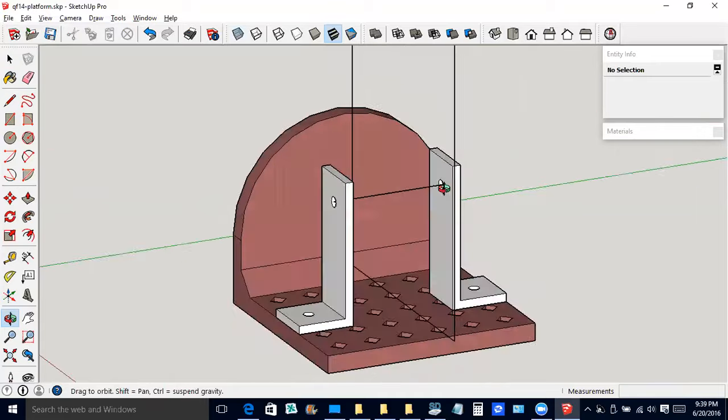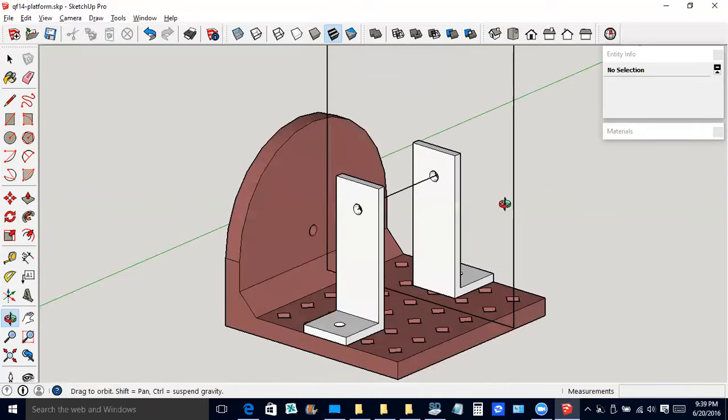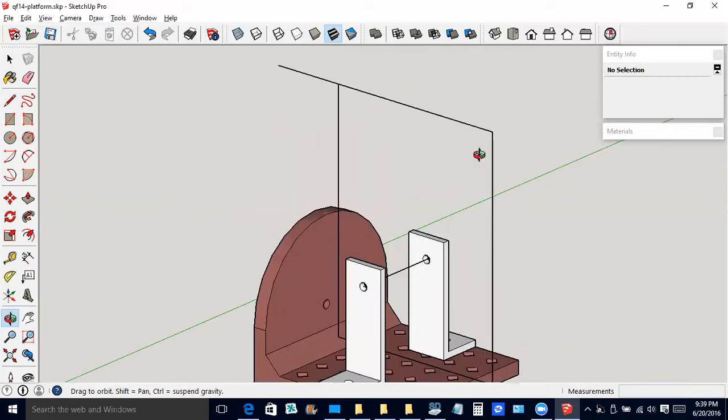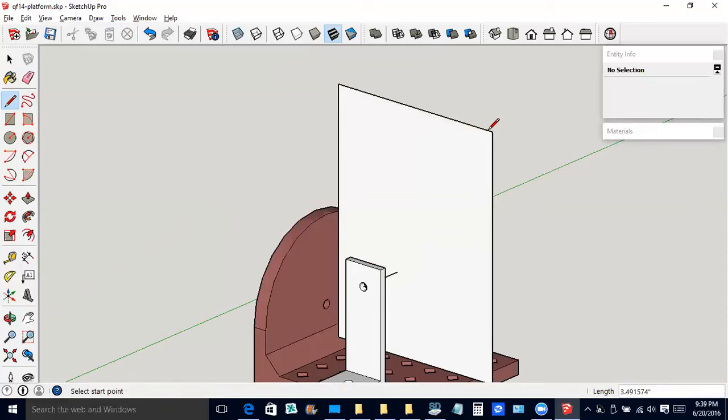And see, I'm really wanting to have a plane that's filled in, you know, that's shaded. And sometimes when you're doing stuff with SketchUp, it fails to fill something in. While I'm at it, I'm going to get rid of this line over here. Now, when SketchUp fails to fill something in, you get the line tool, and you just draw on top of a line that's already there. And see, it filled it in. That's the way to tell SketchUp that, hey, you really want it filled in.